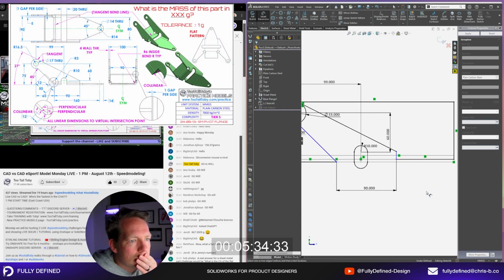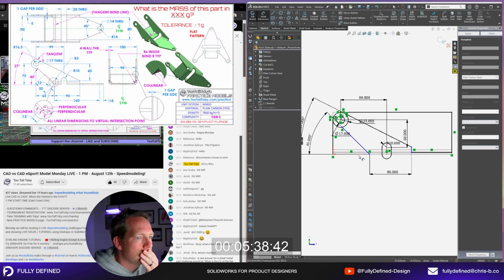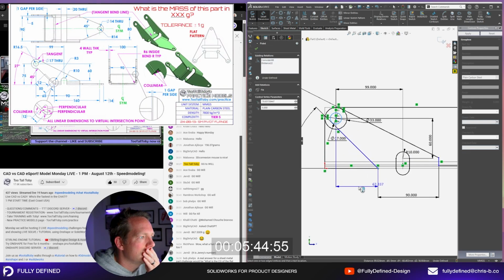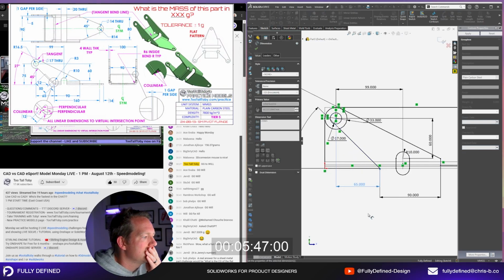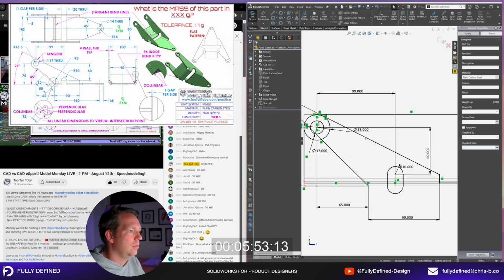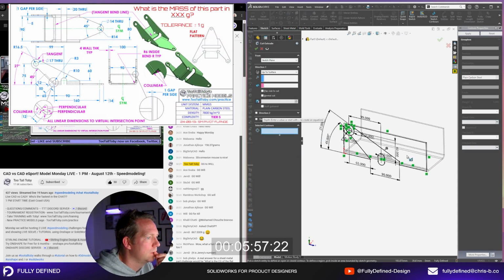Real answer for the sheet metal challenge would be what's the CG of the flat pattern, yeah. And then that becomes tricky too because then you get into K factor and bend reduction, bend allowance, and if there's any little nuances in the different CAD systems that cause those things to solve differently. All right, well, we've got a defined shape. Sheet metal is an interesting one.